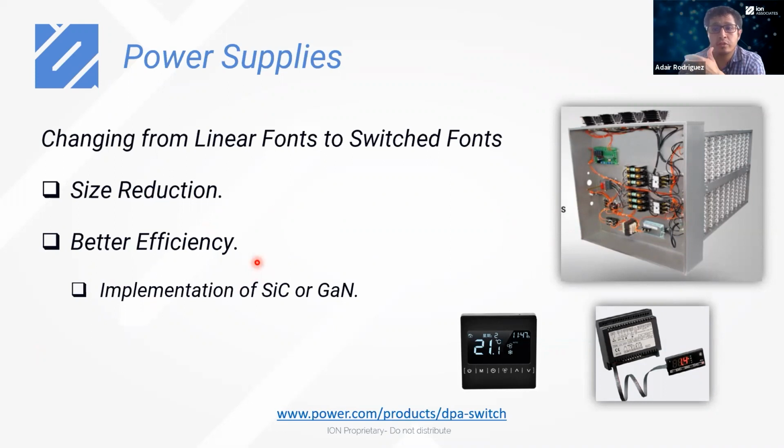This can also be done by changing the technology of these power supplies. Instead of using linear components, a linear transformer for example, we could change to switch mode power supplies, which help us reduce the size and the weight, without using more heatsink, for example. And of course the efficiency can improve with new technology implementations using silicon carbide or GaN.